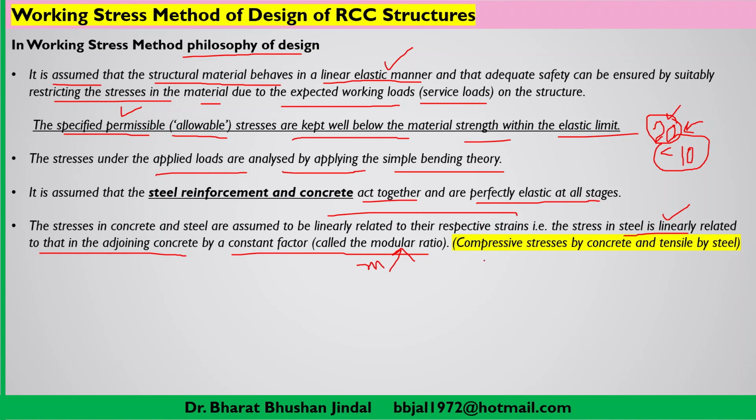Compressive stresses by concrete and tensile stresses by steel, this is another assumption, that all the compressive stresses will be taken care of by concrete and all the tensile stresses will be taken by steel. However, we know that steel can also take some compressive stresses, but in this method we will be assuming that whatever the compressive stresses on the member, they will be taken care of by concrete, and whatever the tensile stresses, they will be completely taken by steel.